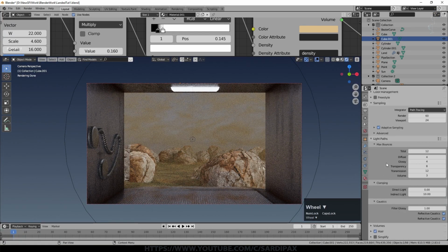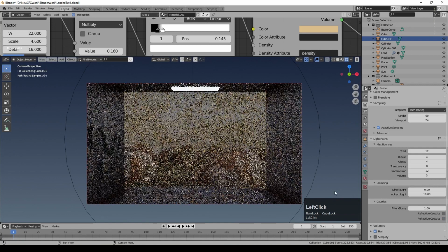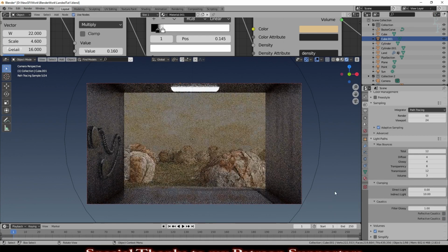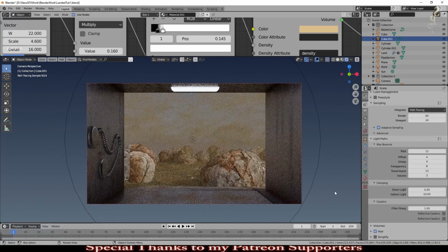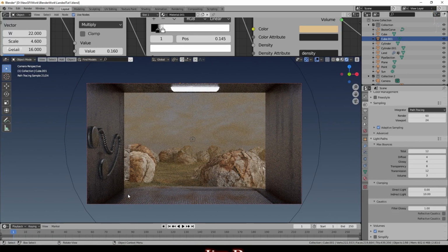And for a scene without glass and water in, we really don't need caustics. They do add quite a bit of noise, so we'll turn those off. And that will optimize it a little as well. You should actually reduce the noise in the scene slightly. Noise being general noise, but also what we call fireflies, which is little bright dots in an otherwise dark area.